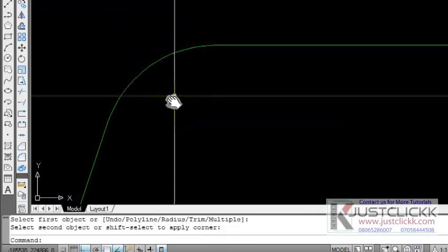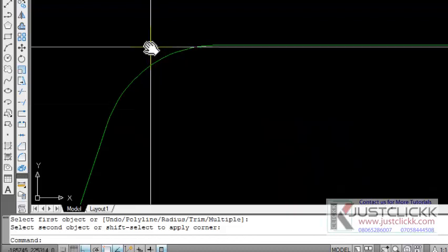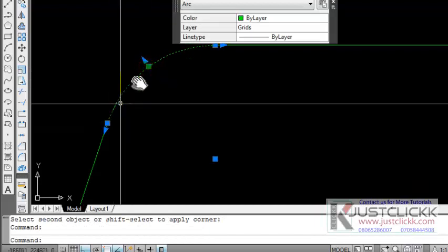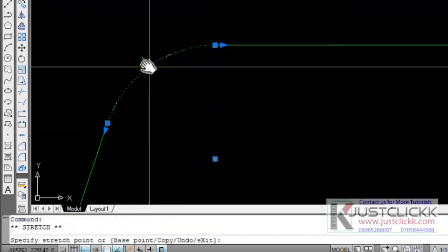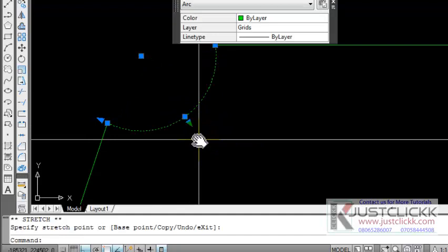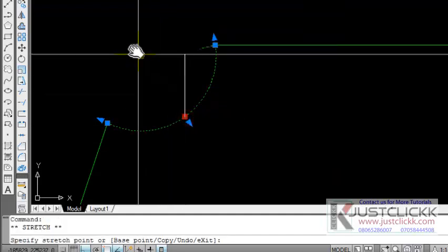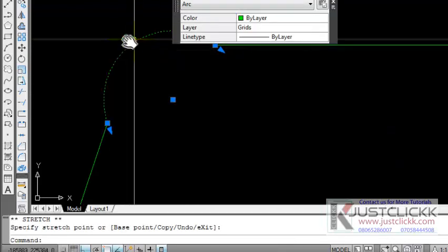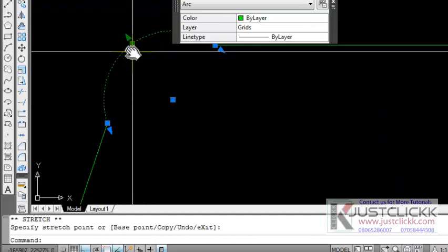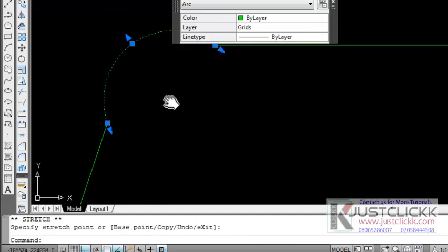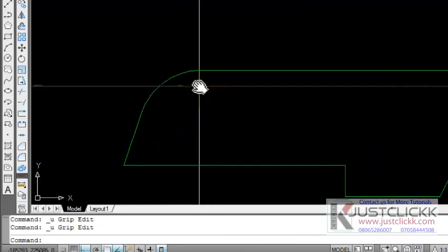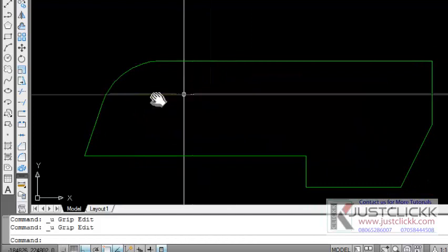And the radius, if you want to modify it, this is the dimension. You know, this is 1 meter. This radius is 1 meter. If you modify it now, you can have a different shape, by clicking on it and dragging one of the nodes here. So it's quite handy, but I don't recommend playing with the curves like that, because they usually have set dimensions. That's why you gave it a dimension there of 1000 radius. So that's how you can use the fillet.